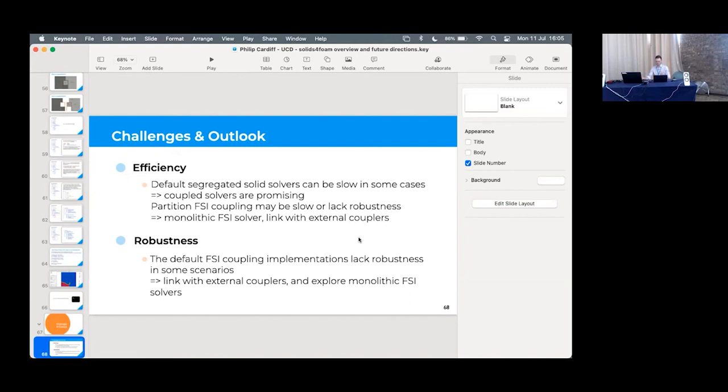But people who are focused on fast dynamics, there's a group that originated in Swansea, and so Antonio Gil, Javier Bonet, a few other guys like that. And they're using OpenFOAM as well now. There's a guy, Gibran Haider, I think he comes along to these sometimes. So they are implementing fully explicit Riemann solver finite volume solid mechanics methods for large strains. So they do something very similar to compressible flow. You have these Riemann solvers where it's a different flavor of finite volume cell centered. You assume there's a discontinuity at every face, and then you resolve that as it propagates around. So yeah, that's for fast dynamics, that's fine.